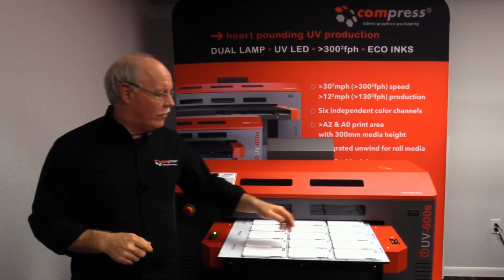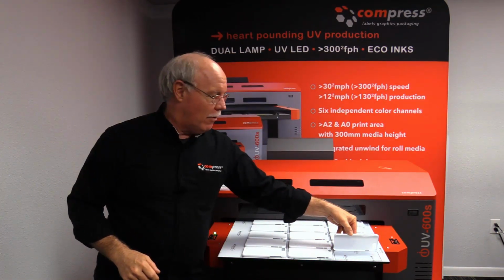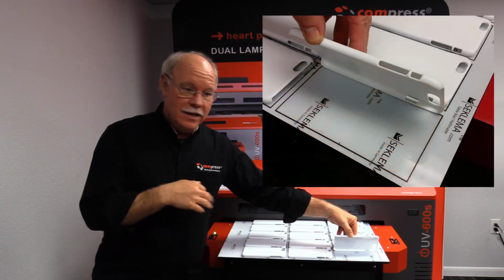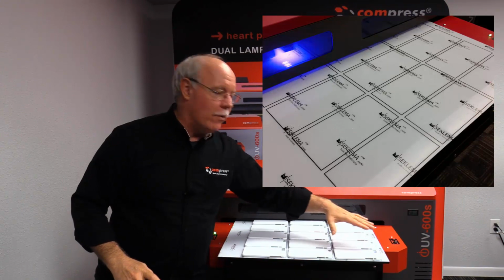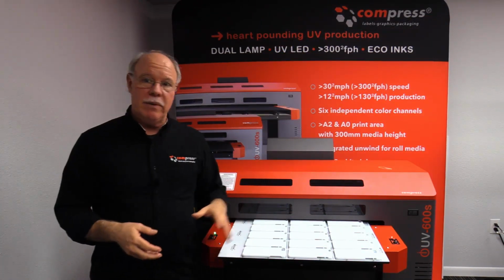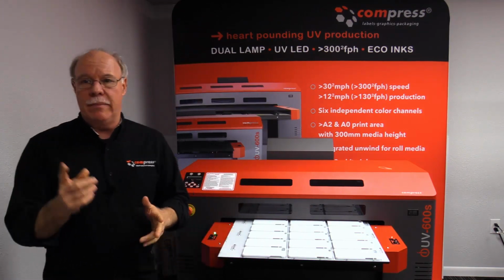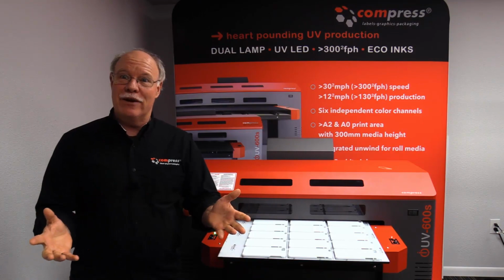What we've done here is we started out and we actually printed out rectangles all over the bed for our representative of our 15 cell phone cases. Then we've actually come in here and just laid these cases in. This is something I would do if I was not going to do a large run continually with these. Otherwise, I'd build a jig. But if you just need to do a moderate size run, one-time type of thing, this is the best way to do it, especially cell phone cases, because they're in so many different sizes and shapes.